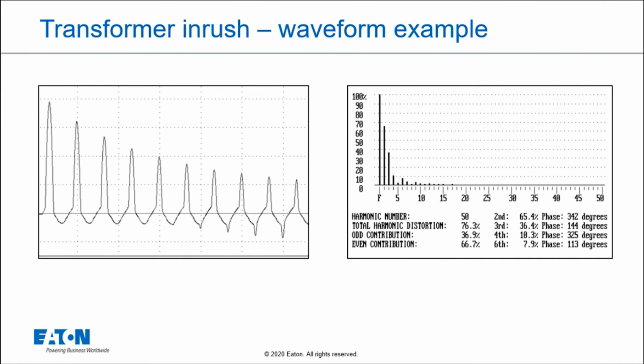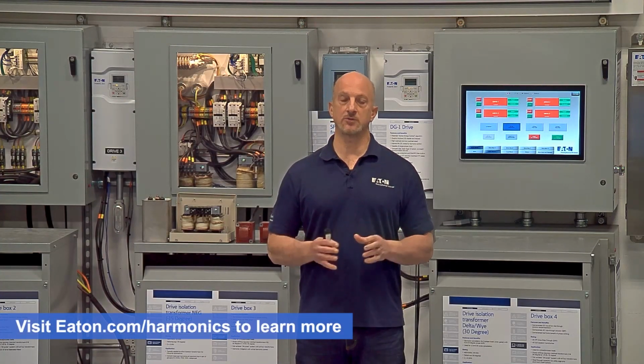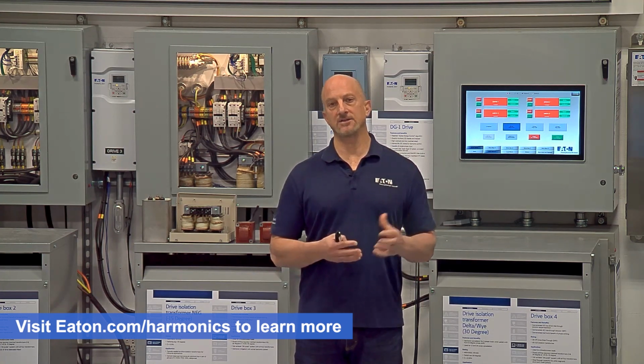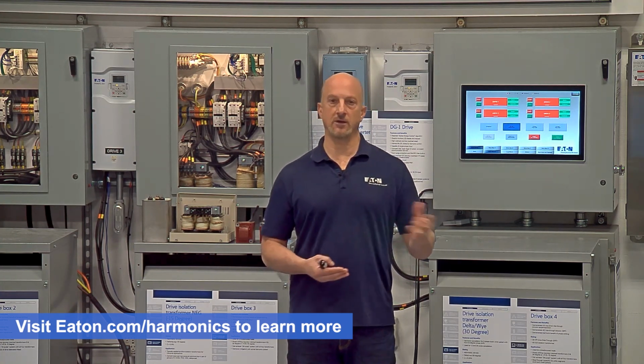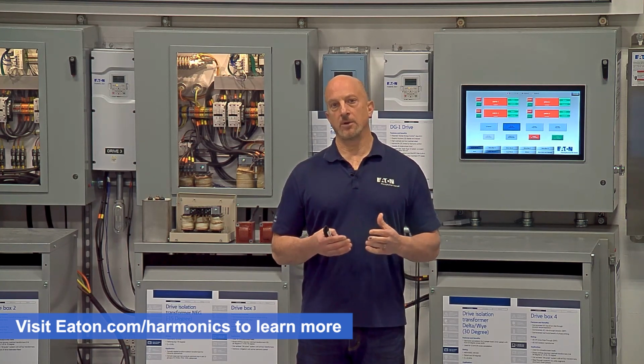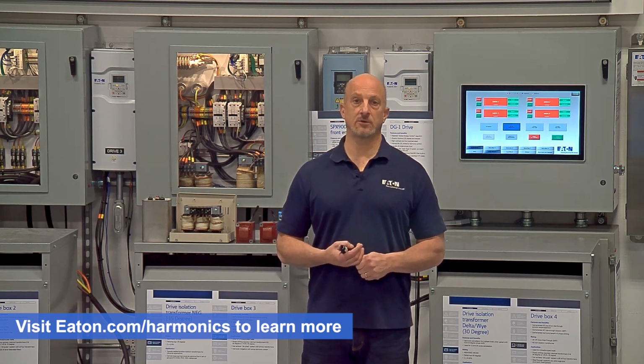So when we talk about transformers, variable frequency drives, and computer power supplies, every one of those things that converts from AC to DC, the rectifiers and things that we see in our power system, anything that's a nonlinear load like that, is going to produce characteristic or typical harmonics. And those waveforms are pretty similar across the board. The magnitude of the harmonic depends on the quality of the rectifier or the system that's built in terms of the current. But again, we can identify those things as very characteristic, very similar across the board.